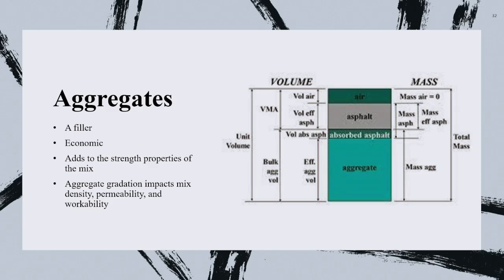And think about the impact. What's going to happen here? Lots of cracking. Because you think you have 5% or you need 5%, you drop down. It's going to impact every property. However, the cracking resistance is the number one property to be impacted if you do not account for this strip of the asphalt that is absorbed. It's no longer free asphalt. It's non-existent. You treat it, it disappears.